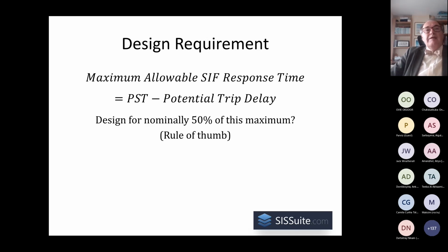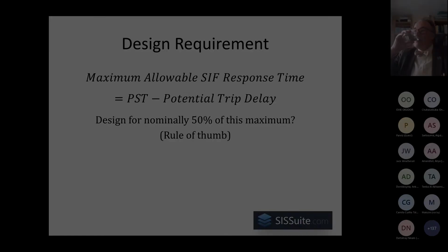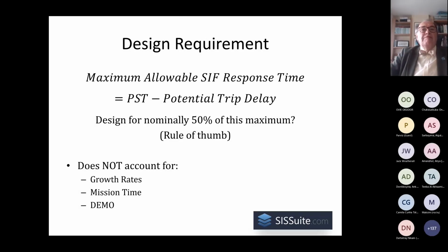And you will often hear talk of the specification, the SIF response time being 50% of this maximum. That's the often cited rule of thumb, but that can be questionable in many circumstances. The difficulty with that 50% rule of thumb is that it does not account for the potential growth, or how fast the response time of the different subsystems within the SIF could grow, and it doesn't account for the mission time of the SIF.